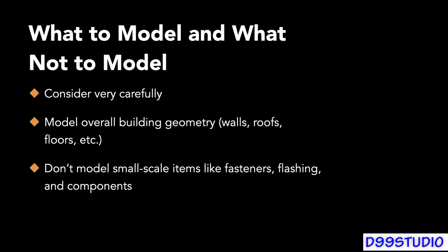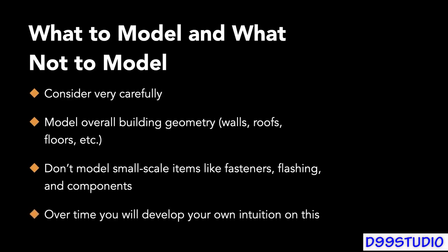So as a general rule of thumb, if an item needs to show in multiple views, then yes, we should certainly model it. But when an item needs to show only in the construction detail, you should think carefully about it and decide whether or not it is worth modeling. Sometimes you will decide, yes, it is, but often you will decide that 2D detailing is sufficient to convey that information. Now, it will take time, but over time you will generate an intuition on this. So it's not going to be immediate, but as you do more of this, you will begin to understand when it makes sense to model something and when it makes more sense to just simply draft it.